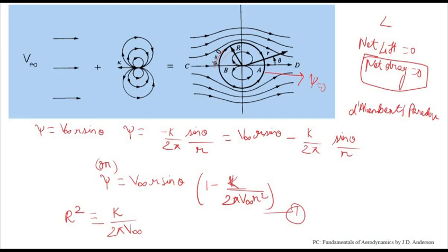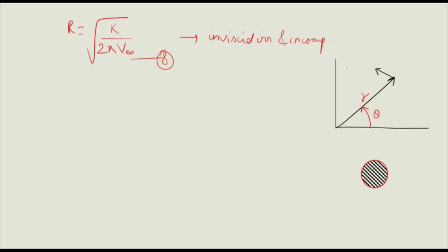So now, as discussed, D'Alembert was the first person to note this difference. Now, this inviscid theory predicts that the flow is smooth behind the cylinder, there are no wakes, and it leaves the cylinder smoothly, and there are no asymmetries, which results in 0 drag. But as we saw, that is not the real case.